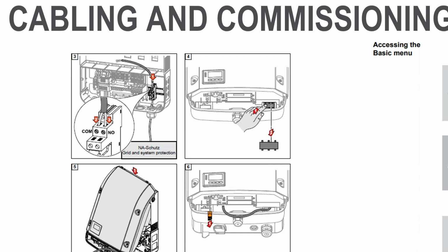Now, the S0 switch is actually situated on the reservoir, which is on the inverter main body. As you can see from this particular illustration, we can do this installation only on the wall mount bracket of the Snap inverter, which of course has the DC and the AC contact points. So in order to take care of this challenge, you'd have to break out this serrated perforation.